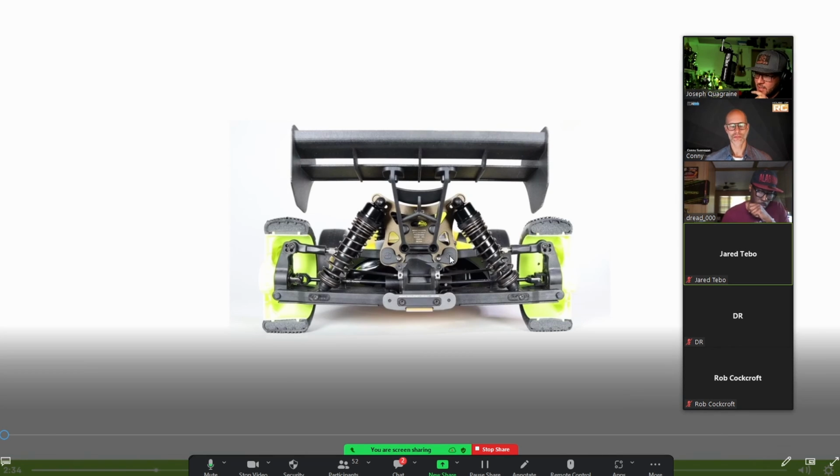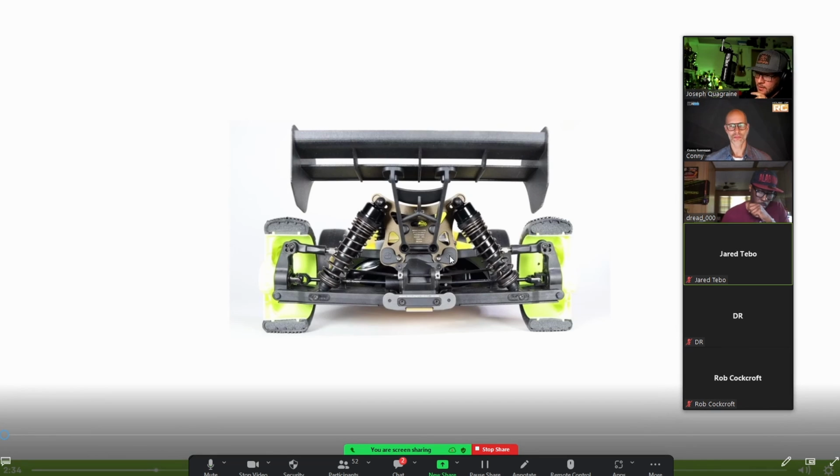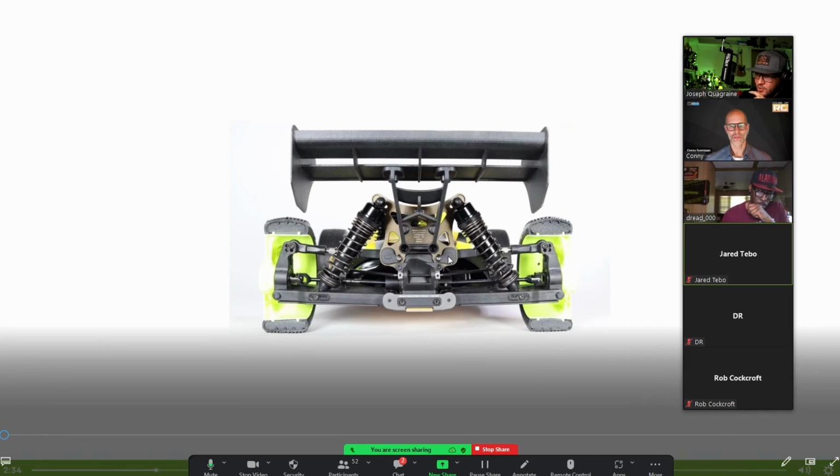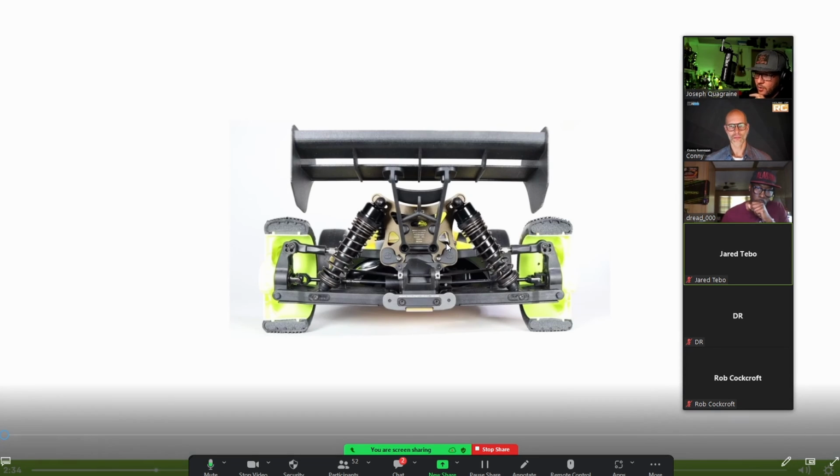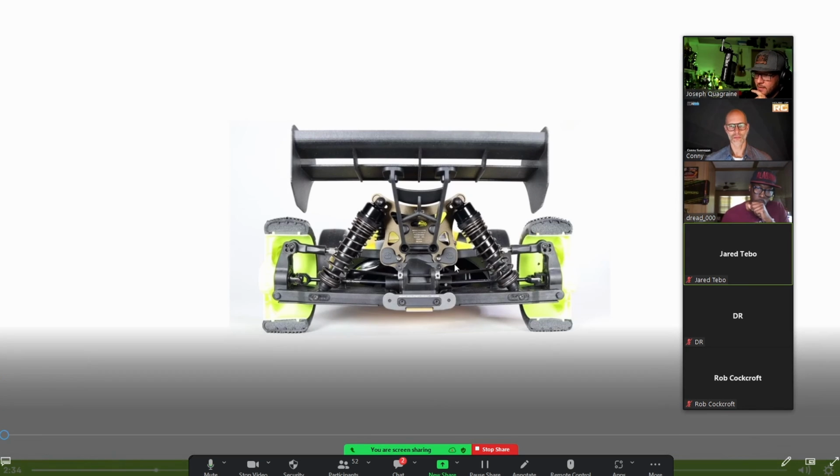And that's exactly how Jared explained it also. High grip track, I would move the link up to lower the roll center to have the car more in the track. So with the link, I really think about in or on the track. The sort of roll center height, thinking of in or on the track, that's what I do with the link on the tower.